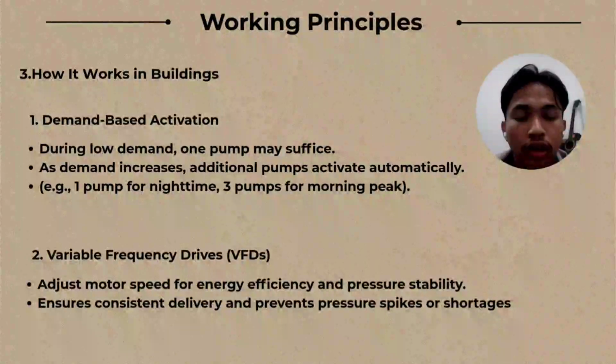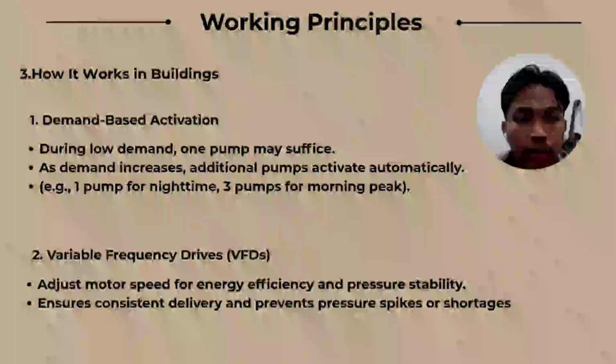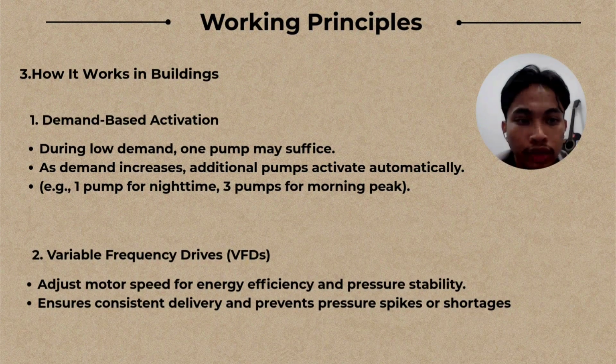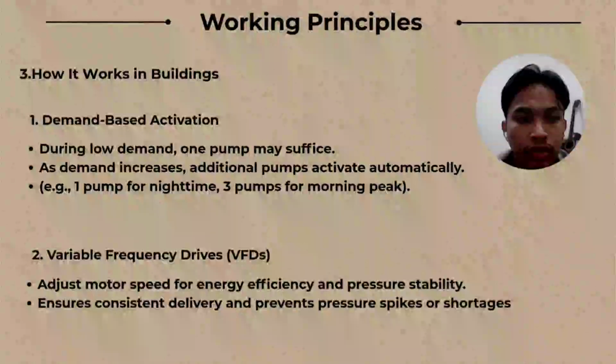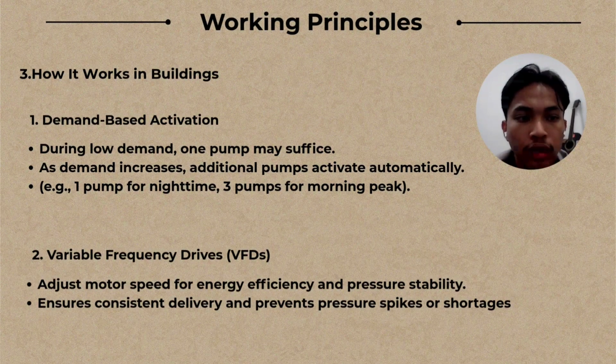And the third is the variable frequency drive, so VFD. To make this all even smarter, we use a variable frequency drive. The VFD adjusts motor speed based on demand. So they help maintain steady pressure, improve energy efficiency, and reduce wear on equipment. This prevents pressure spikes and shortages, ensuring a reliable water supply.